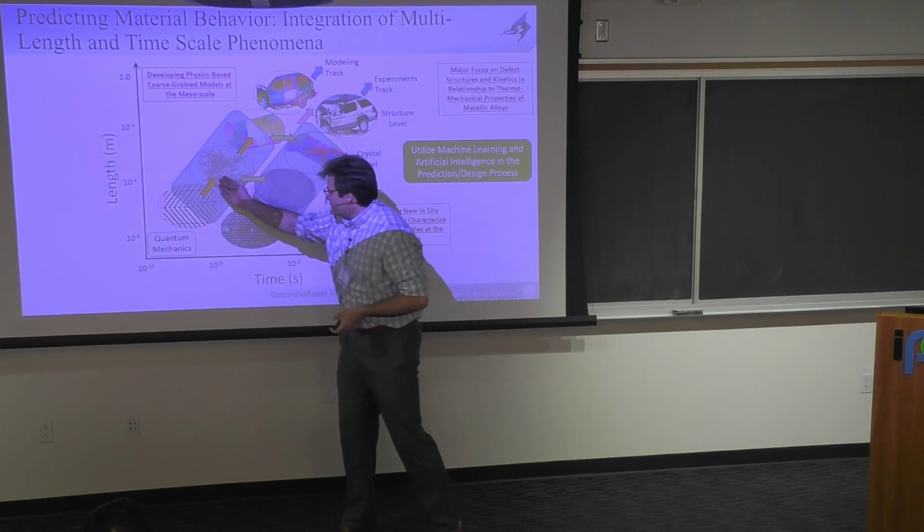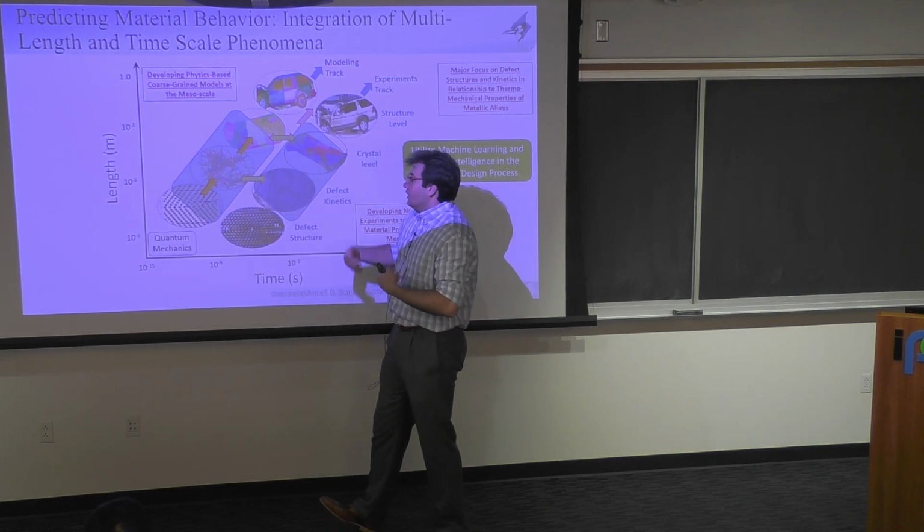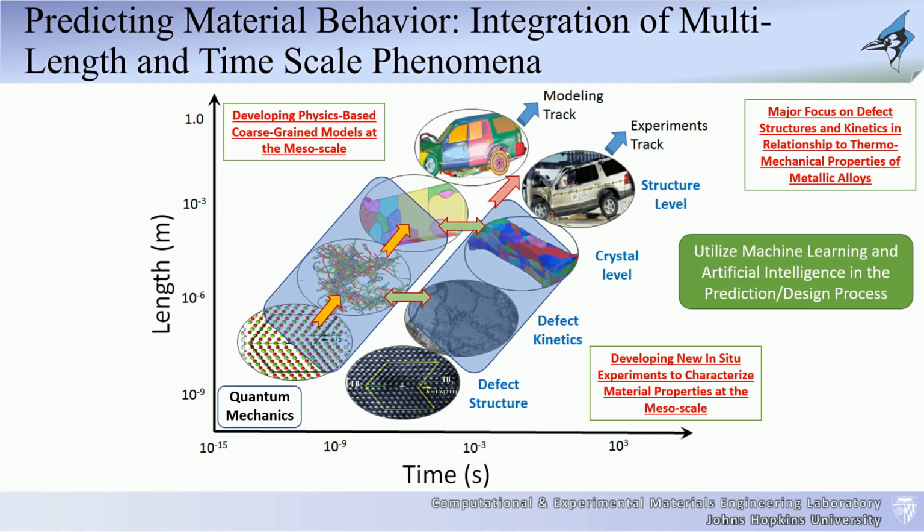As I showed you, there are dislocation structures that are forming. And what we're going to try to do is look at that specific scale. The reason that we look at that specific scale is because we can actually look at evolutions of dislocation structures at the microns scale, tens of micron scale. Atomistics is great. It actually has less assumptions than what we do in discrete dislocation dynamics. I'll talk to you in a minute about what we do in those kinds of simulations.